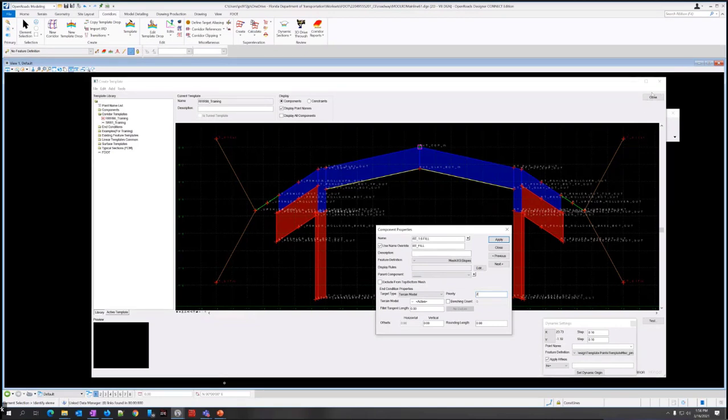it'll say, look as far out on this slope, and if you don't find the existing surface, well, I'm giving up. That end condition was not fulfilled. So now you're going to try the second priority, which is the fill. So this is just which order it's going to do it in. So if one doesn't resolve, the other one will. But generally, you do not want them to be the same priority.